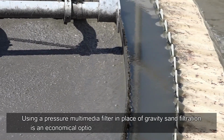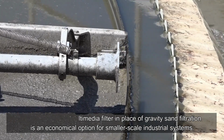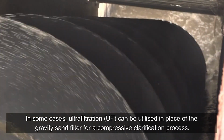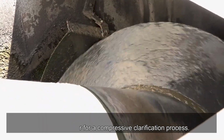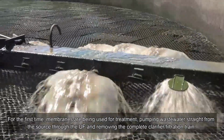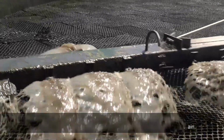Using a pressure multimedia filter in place of gravity sand filtration is an economical option for smaller-scale industrial systems. In some cases, ultrafiltration (UF) can be utilized in place of the gravity sand filter for a compressive clarification process. For the first time, membranes are being used for treatment, pumping wastewater straight from the source through the UF and removing the complete clarifier/filtration train.